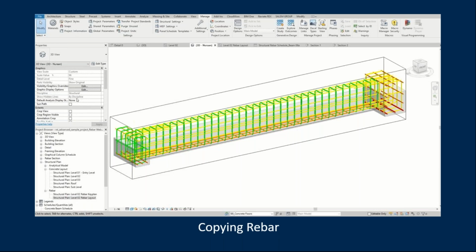If anybody is still not yet on rebar in Revit, in the more traditional packages you could just detail it once and then change the member number or the number of, and it will just multiply each thing. But in Revit, you need to have the actual element present in the model to be able to schedule it and to have the right amount of bars in your schedule to send off to site. There's some debate around that because it's not what you're used to in particular, but it is also a way to limit mistakes. You'll never have a counting problem because everything that you're sending to site is in your model.